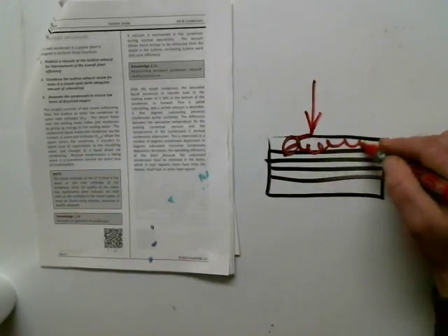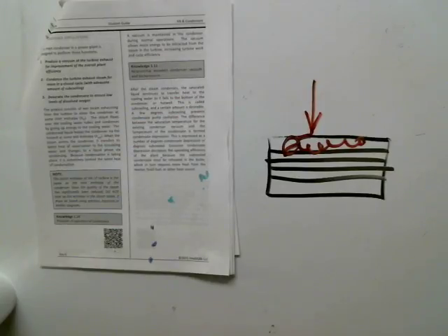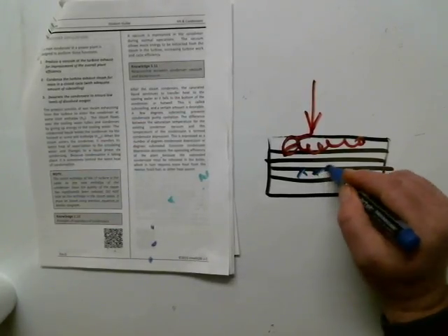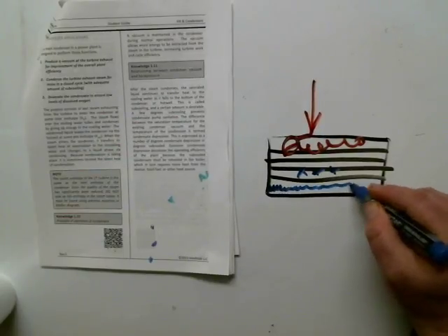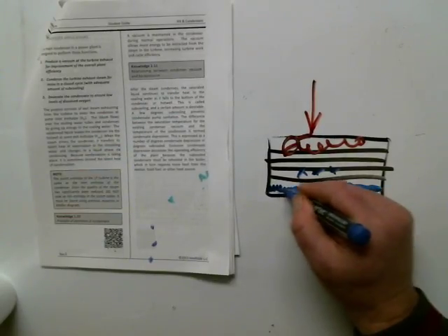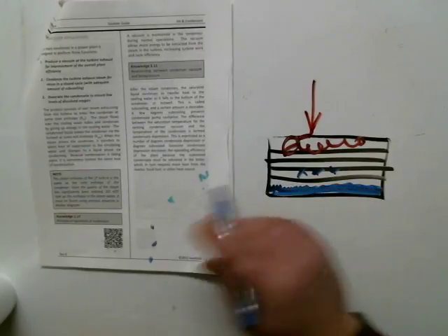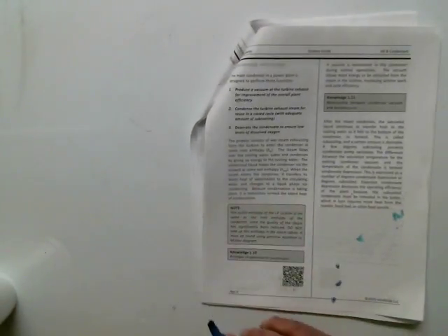There's all this steam in here, and now it's water right about here, let's say. So I got blue water, and then it actually subcools, and I end up with some subcooling, and that allows me to prevent cavitation of my condensate pumps.